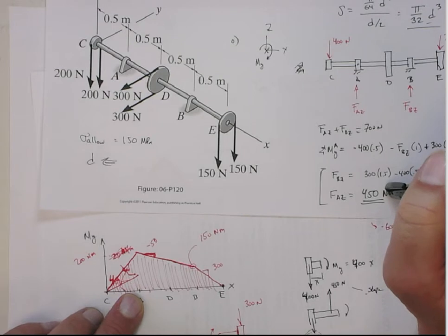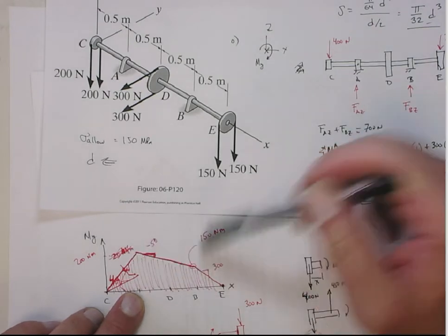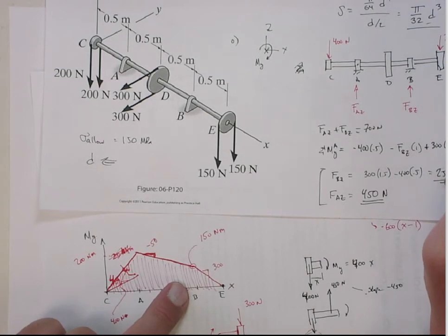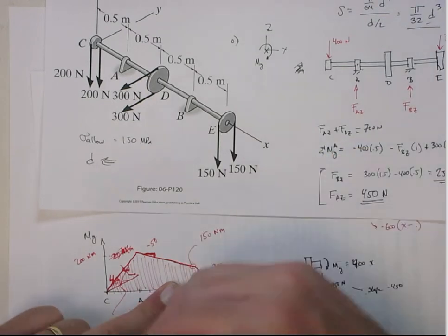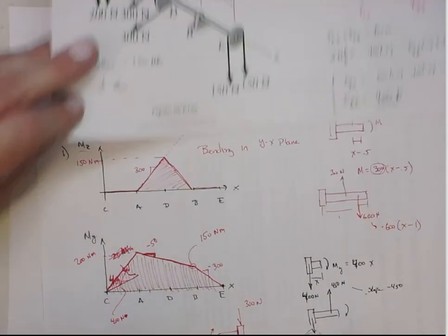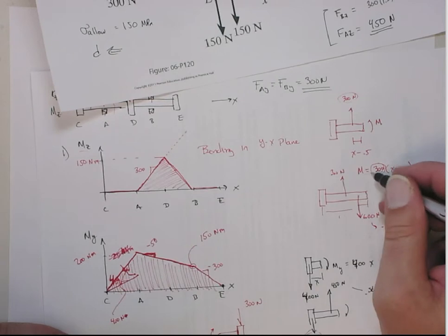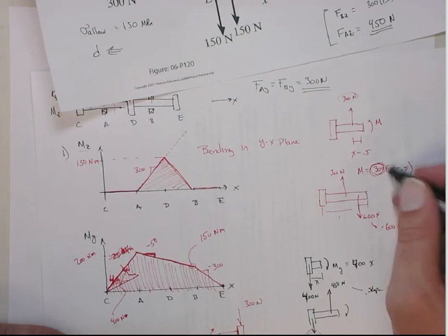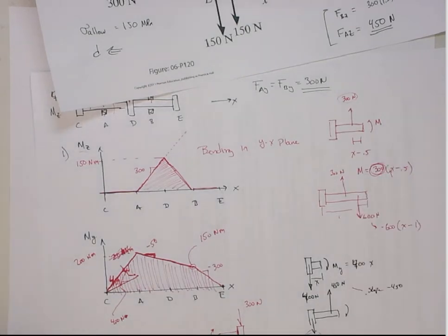So the net slope is minus 50. The next place you get a point force isn't until B. That point force is 250. So minus 250, minus 50. So that comes down here at a minus 300. Okay? And the reason that works is because when you look at the moment arms, you're always going to have the force multiplied by the moment arm, which is x minus something else. You'll never get an additional factor in here. So the slope is always going to be equal to the value of the point force.